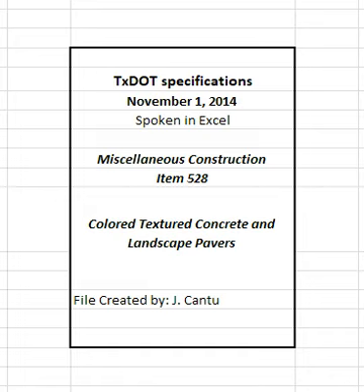5.4 Removing and relaying existing pavers. The work performed and measured as provided under measurement will be paid for at the unit price bid in accordance with remove and relay pavers and replacement pavers. Base required for landscape pavers will not be paid for directly but will be subsidiary to this item. Paver units damaged during removal, loading, transport, or compaction will be replaced at the contractor's expense.